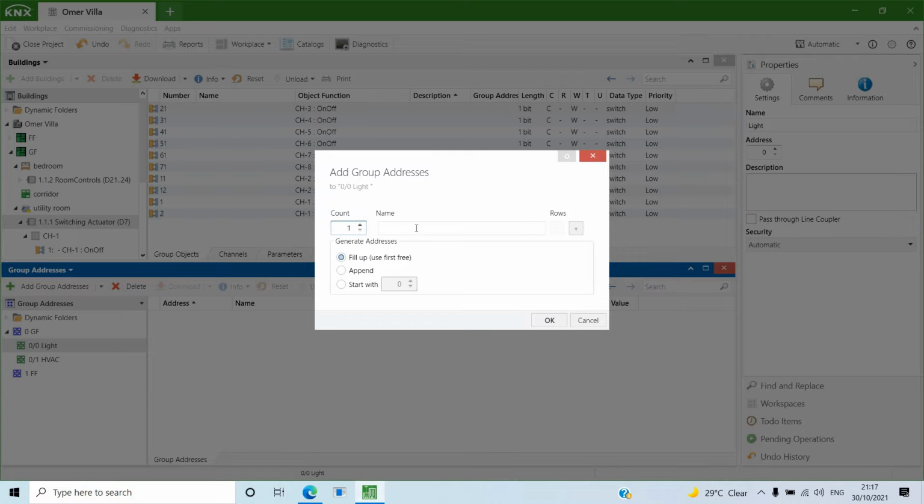You can now start creating your group addresses. What we have here is bed 1. Same here, you can write also bed 1, toilet, on off. You can name any name you want actually, but for easy understanding, you can even leave it empty, but for the purpose of easy understanding, you can monitor the group through the telegrams. You understand actually the system is working or not working.